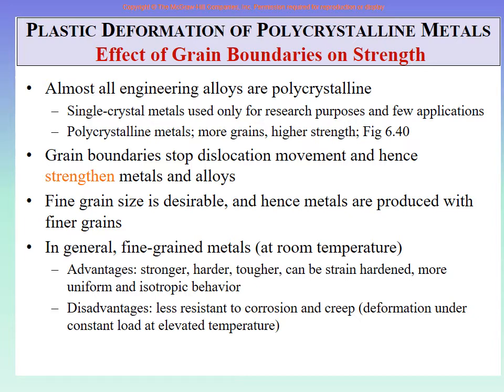So this is a brand new piece of information for you. When we go into the crystals chapter, we will cover it more. But right now, it is the same material. It is one type of steel or one type of aluminum alloy. But when we process it, when we manufacture it originally, if we can control the size of the crystal, the size of the grain, then we can change the strength of the same material. Do you understand? This is remarkable.